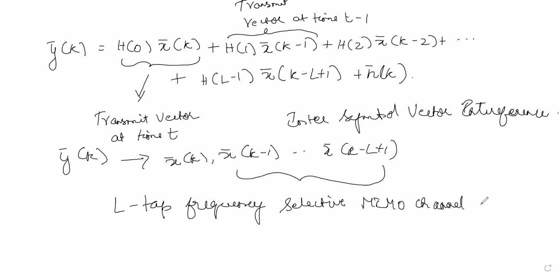In a MIMO OFDM system, one needs to perform the inverse discrete Fourier transform, or inverse fast Fourier transform operation, at each transmitting antenna. So now we are going to combine MIMO and OFDM and see the transmitter schematic of this MIMO OFDM.